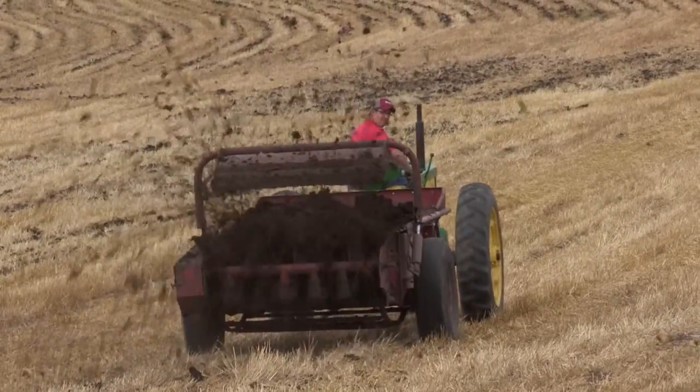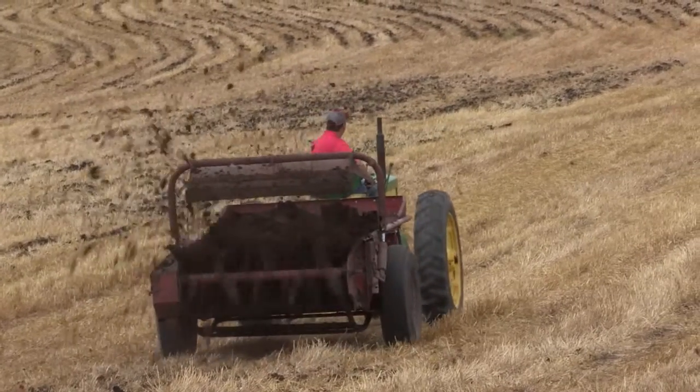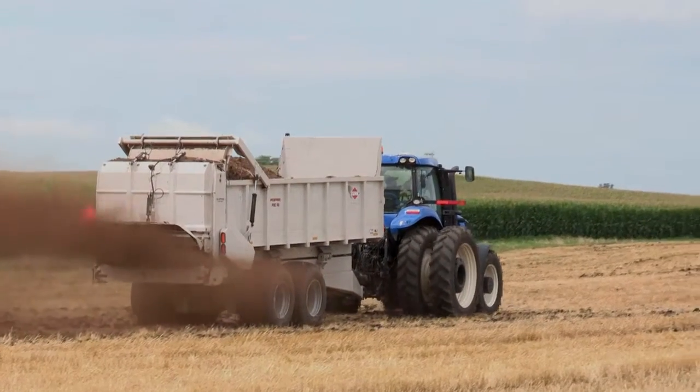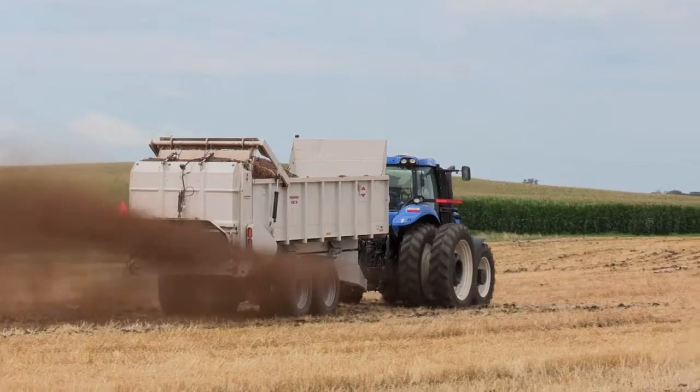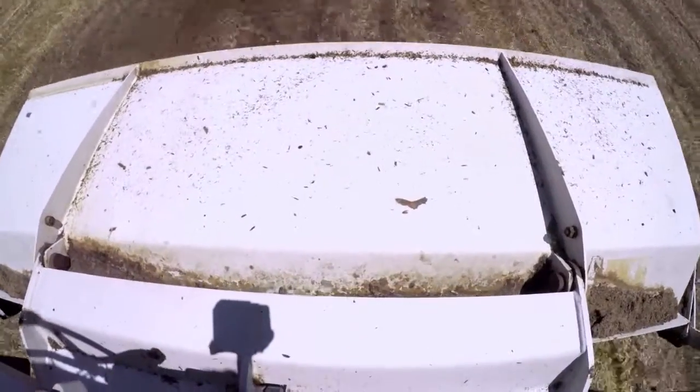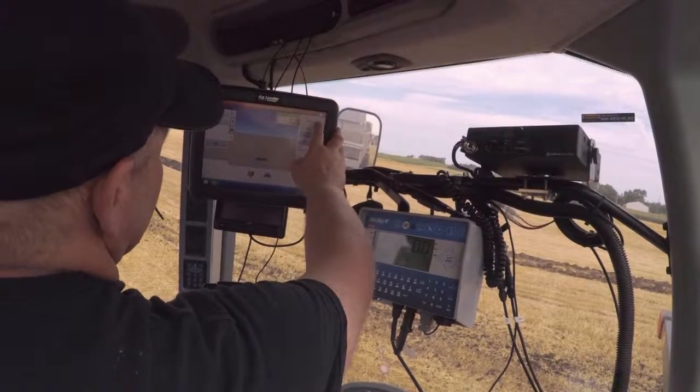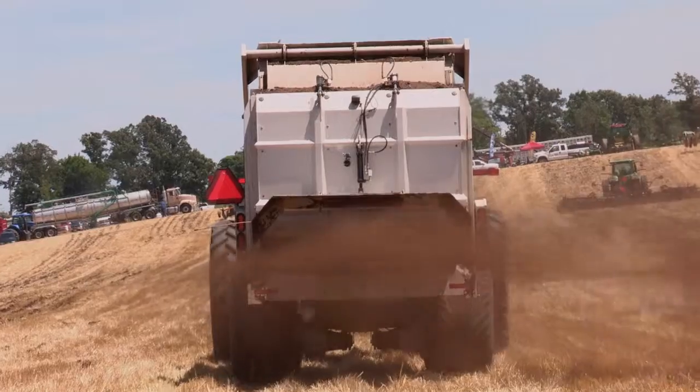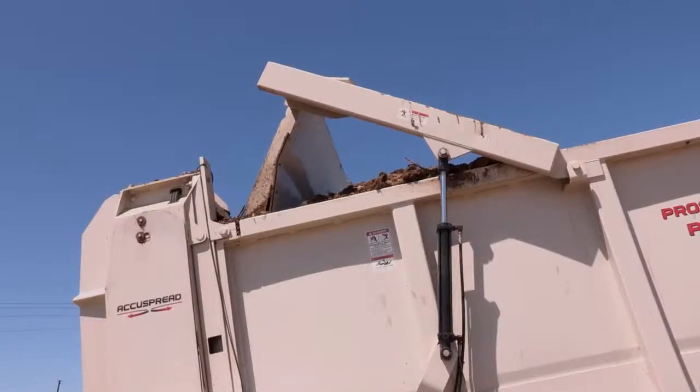Finally, solid spreaders are used for poultry manure and sometimes livestock manure that is mixed with bedding. Solid spreaders can only surface apply manure, but it can be incorporated later with tillage equipment. The application rate for solid spreaders is calculated in tons per acre. The application rate is determined by your tractor speed, equipment components, and density of manure.